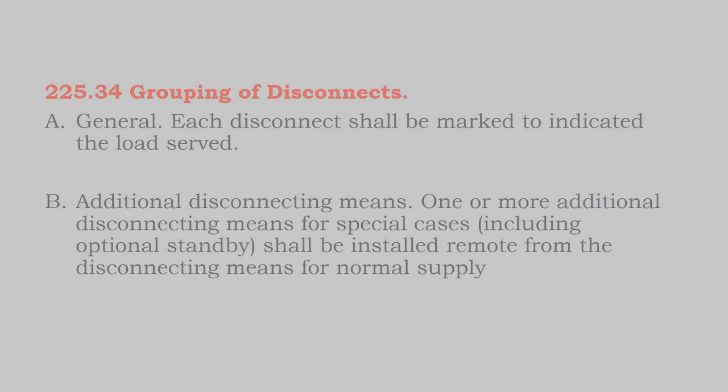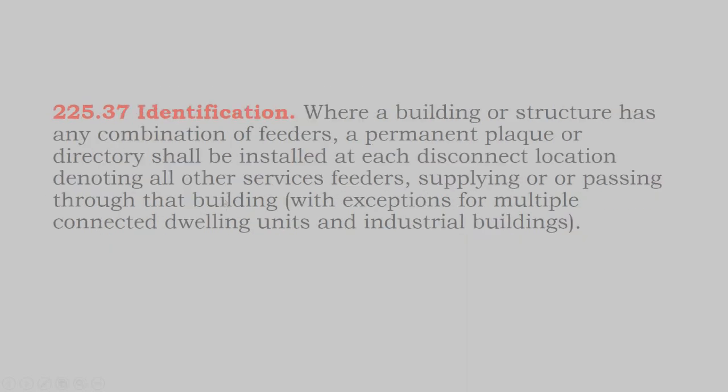Now, also, those switches need to be grouped in the same location. And so what that means is you can actually have 6 normal grid connected solar power switches, or your utility main, and 5 line side connected solar arrays as well, all grouped together. And then you can have 6 additional switches for various battery banks on the outside of the building, for various battery banks and generators for your backup power systems.